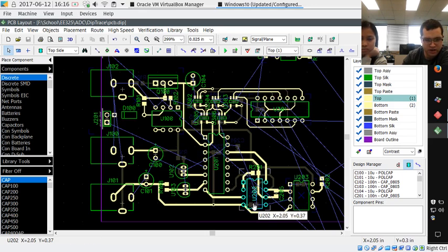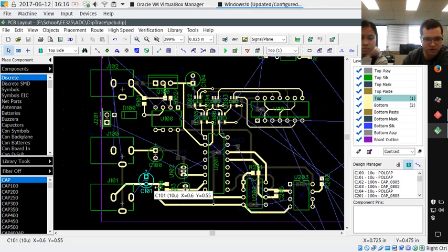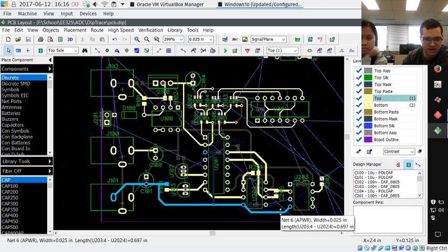and this here is the op-amp integrator and buffer. It's a 2 op-amp package, the TL052, which we chose because it has a fairly low offset, but also because it is moderately fast, which means that it can handle the rapidly changing switch input.